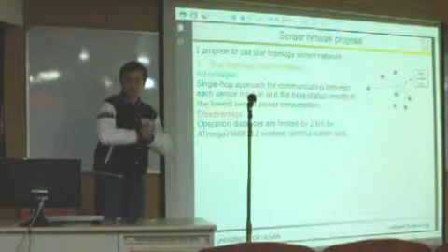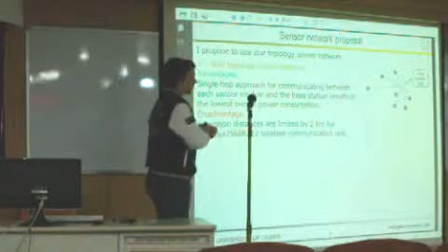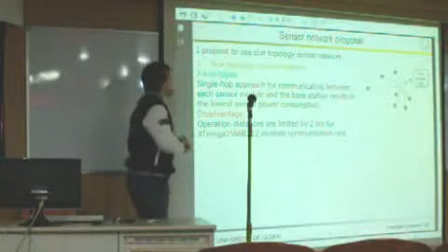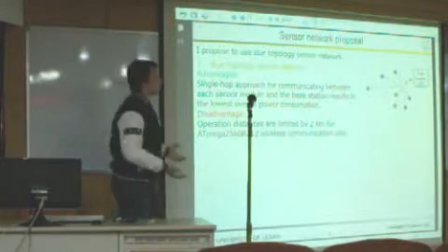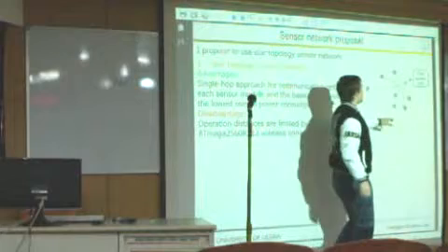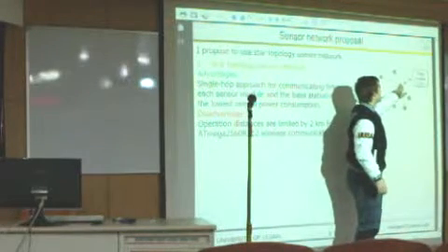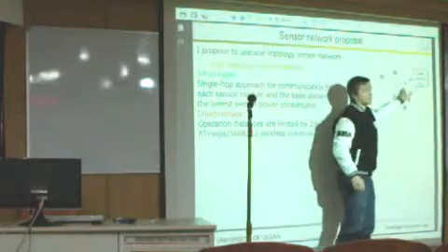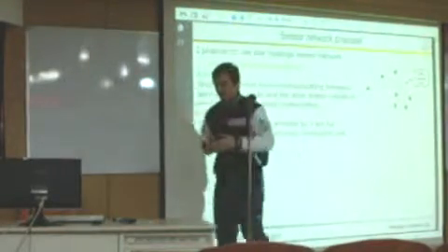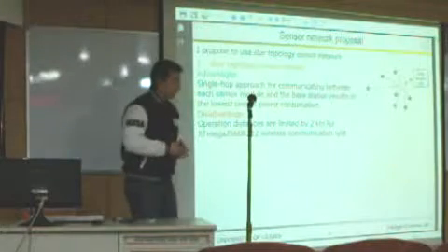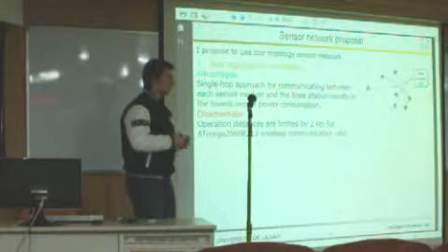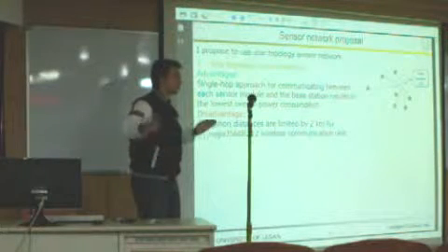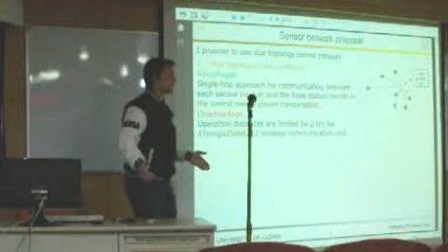I'm going to use a sensor network. I'm choosing between a star topology sensor network and a mesh topology. The advantage of star topology is we have one data handler and sensor nodes which can communicate directly to the data handler. We could use this topology if we had communication transceivers which can work within maybe 1 kilometer or 2 kilometers.